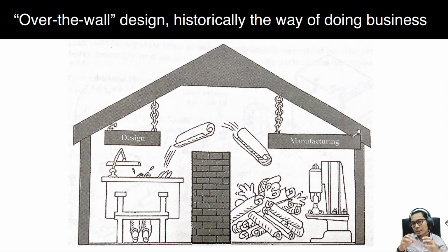So in DFMA, it is important for you to involve the production engineers and all the manufacturing people in the early stage and in the development process of the product, so that these expert people from the manufacturing team can share their opinions on the capability of the processes they have, based on their knowledge, to produce the design that you imagine.